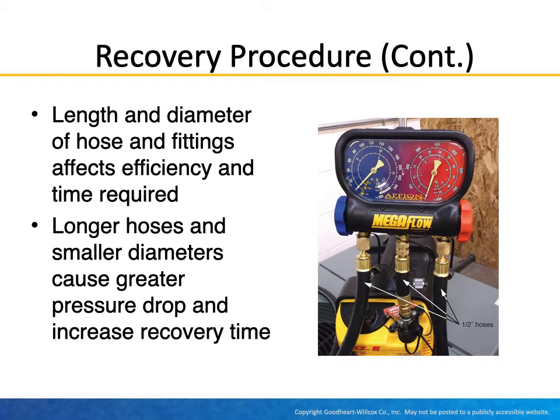Recovery procedure. Length and diameter of hose and fittings affects efficiency and time required. Longer hoses and smaller diameter hoses cause great pressure drop and increase recovery time.